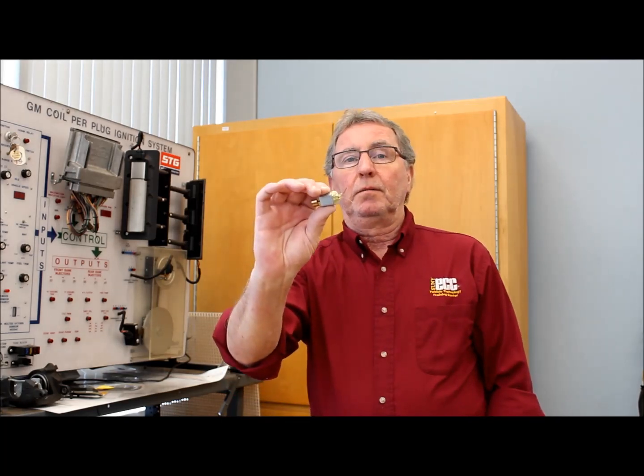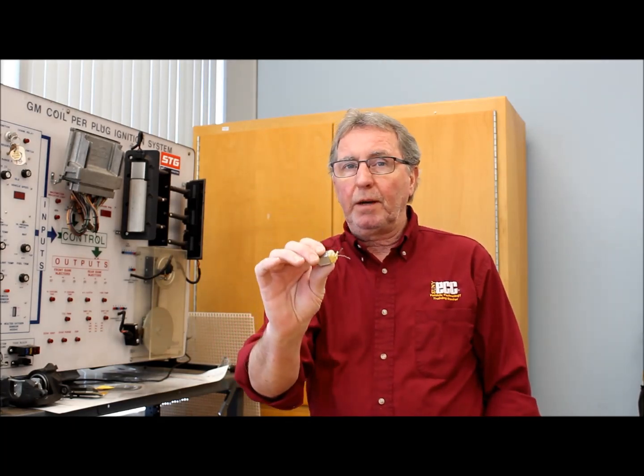What have we learned so far? One thing we've learned is that there's two ways that motors can be controlled by a computer. There's direct control. Now the problem with direct control is all of the motor's current is running through the computer circuitry, which is small and delicate, so it can't handle a whole lot of current flow. A little motor like this, maybe. This was, what, 1/4 of an amp? I don't remember. That's something you've got to put in your report. When you watch this video, write down numbers. So that can be controlled directly, small current flow.